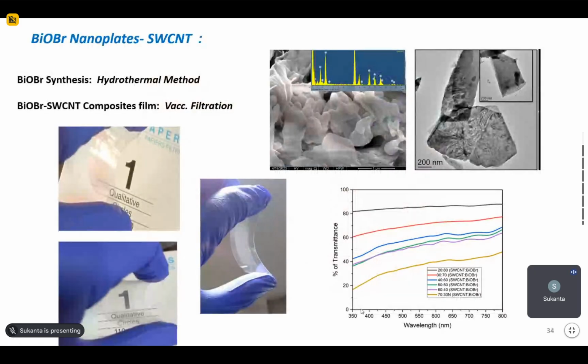Now, when we have this type of transparent conducting film, that transparent conducting film can be used as a current collector for a supercapacitor to make a transparent supercapacitor. We can make the active material, like carbon nanotube or carbon and oxide material composites, very thin to make it transparent, and with the transparent current collector the total device will be transparent because you generally use a polymer gel electrolyte which is also transparent.